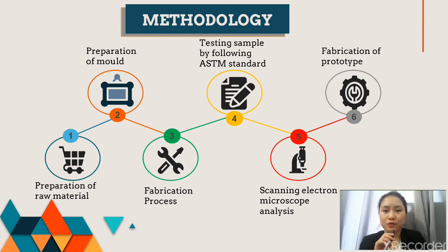The second test is fire testing. This testing will use a fire torch as the fire supply to shoot on the surface of the sample. The purpose of this test is to watch how a flame spreads across a sample in order to determine the material's relative burning behavior. The duration for this testing is 10 minutes and the distance between the sample and the fire torch is 10 mm. Therefore, the evaluation will be the time taken for the sample to react to the fire.